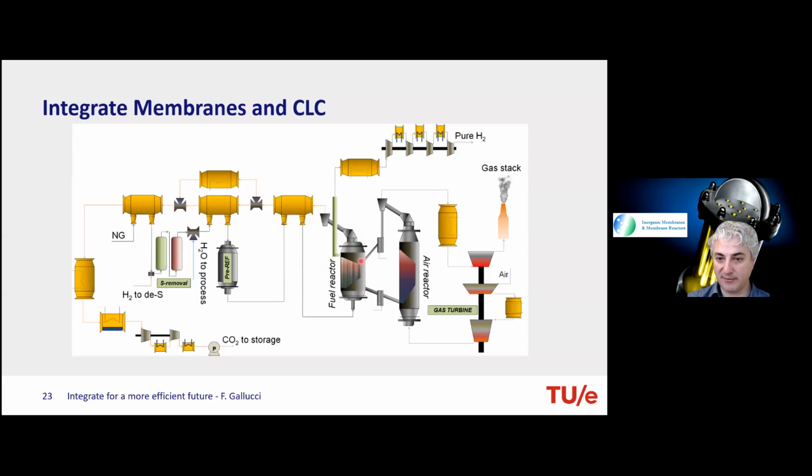If you take a membrane reactor, since the flux through the membrane is driven by a delta P, of course, hydrogen will be produced at low pressure. So you have to also add the compressor. If I don't put this compressor here, I could say that this hydrogen is much cheaper than the steam reformer, but it's not true, because you have to put the compressor and you have to calculate the efficiency and the electricity that you use. Anyway, we did this, and we did it with Aspen.